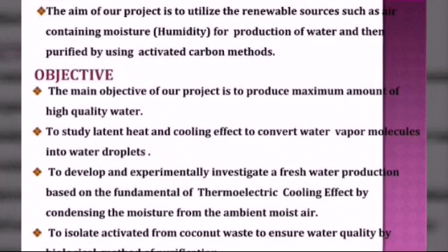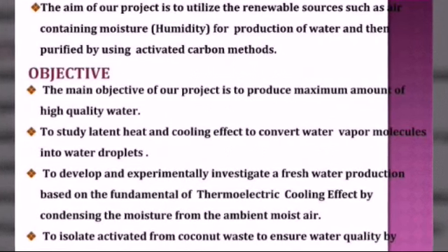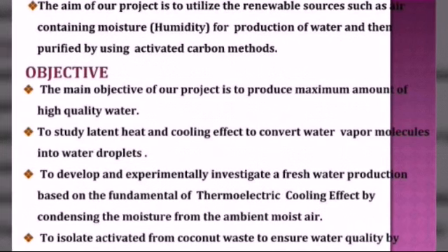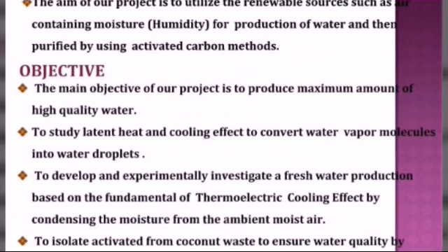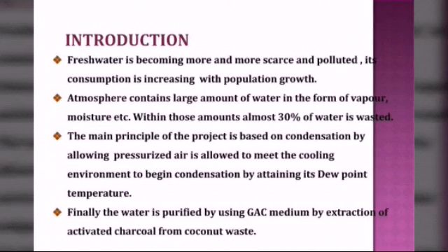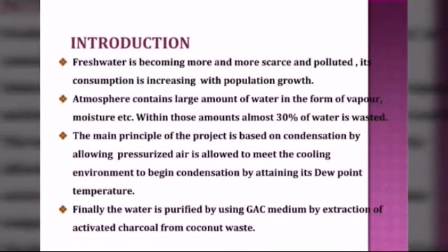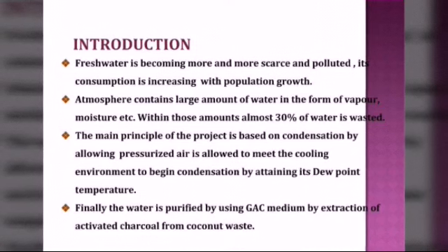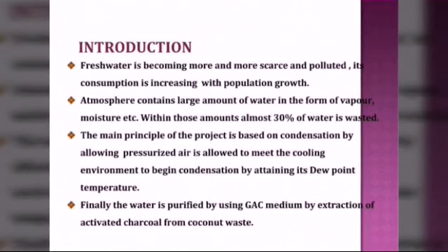resources. The main principle of this project is based on the condensation principle, by allowing the pressurized air to meet the cooling coil to become condensation by attaining its dew point temperature. Finally, the water produced from the cooling condensation is purified by using the activated carbon that is extracted from the coconut waste and is activated by using chemical treatment.